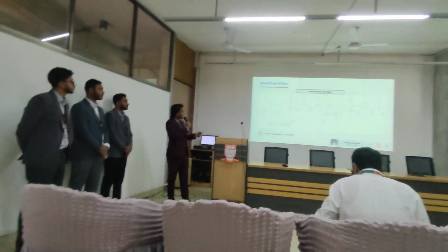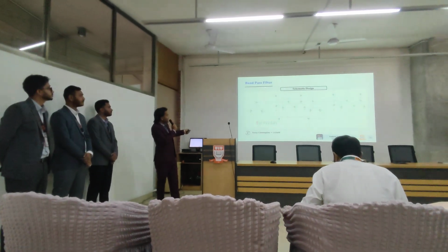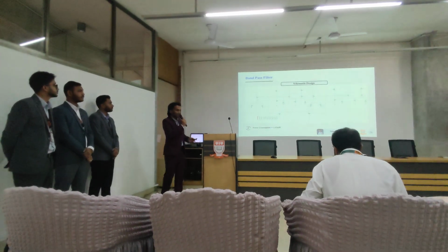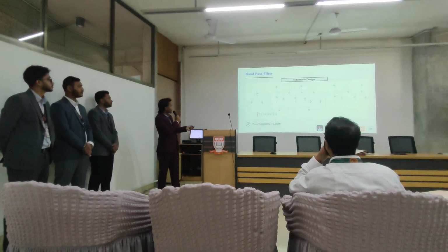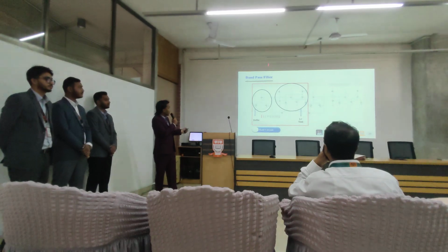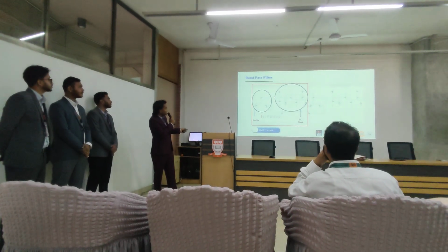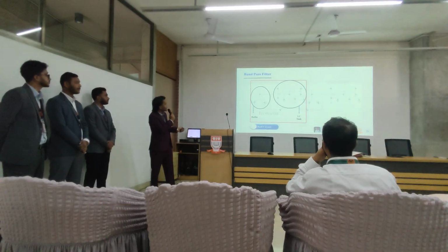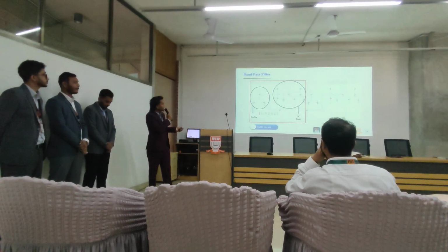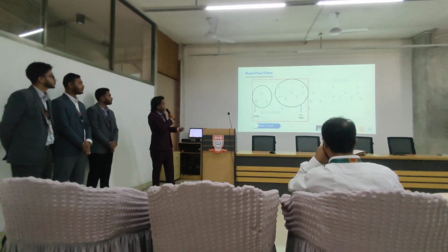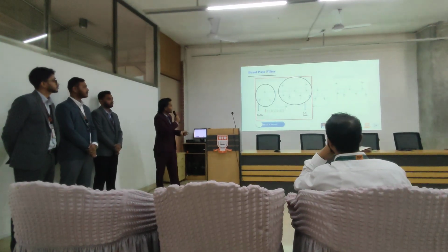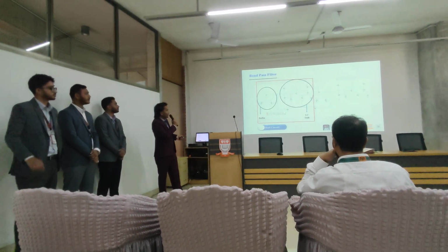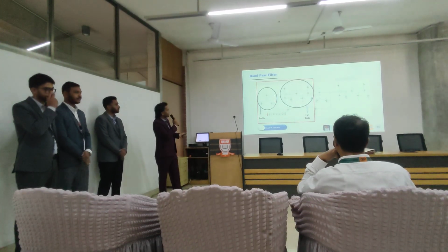As you can see here, our gyrator is basically a differential circuit. This is the positive half and this is the negative half. So I am just going to explain the first half of the circuit. The core of our filter is the central gate node, and we cannot just put the RF input voltage into this node because this node has a massive impedance at resonance. So we have used this transconductor to convert our input voltage into an AC current that pumps straight into